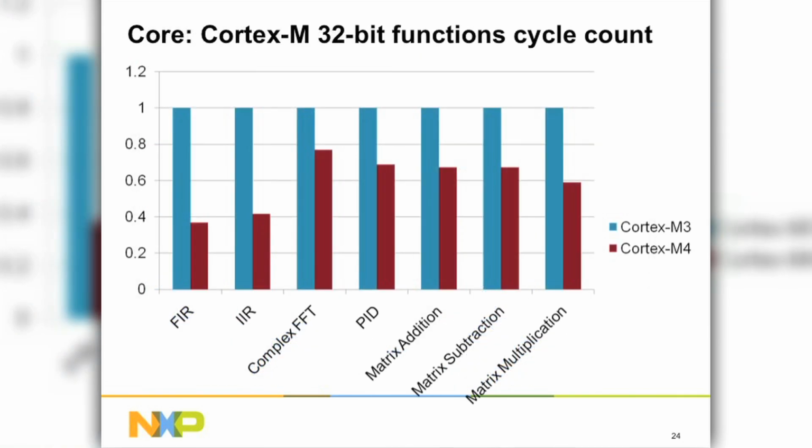So quickly, let's compare. As I mentioned, the M3 can do signal processing, the M4 can do it better. So you might still not need an M4 if you're doing basic signal processing. But let's look at a comparison of the differences. So the M3, as you see in the blue here, smaller is better in terms of the number of clock cycles to do an instruction.